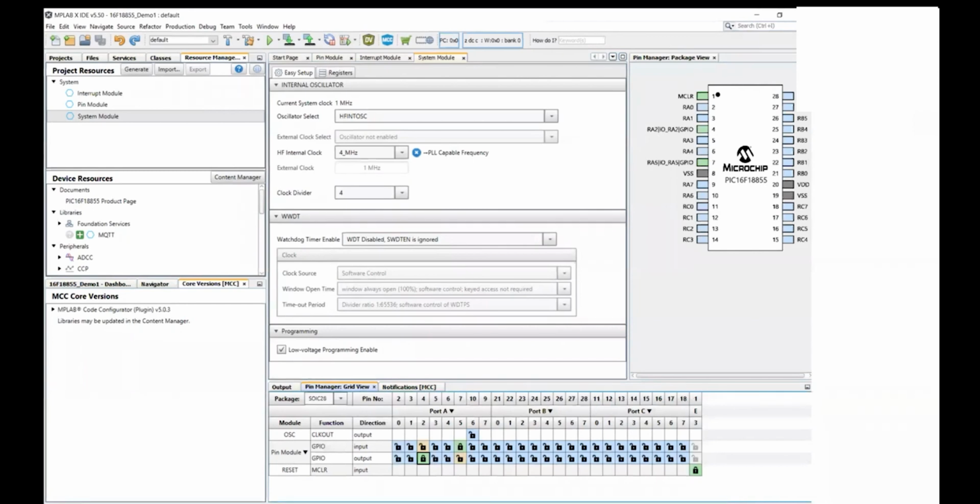If you look carefully at port A, I've selected port A pin 5, which is pin 7 of the chip. And I've clicked a wee padlock on it, so I want that to be an input. And in the line below, port A pin 2, I've clicked on that padlock.